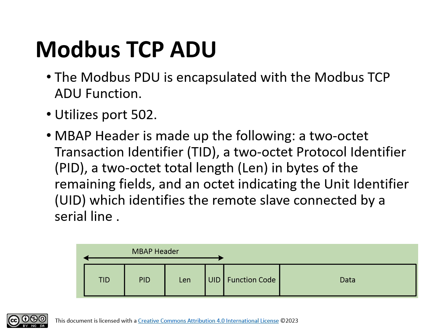The Modbus organization, modbus.org, extended the Modbus protocol to work over the Transmission Control Protocol, TCP, by encapsulating the Modbus PDU with the Modbus TCP ADU. The protocol is registered to utilize port 502 and is realized by augmenting the standardized Modbus PDU with the Modbus Application Protocol, MBAP header, as shown in the figure below.